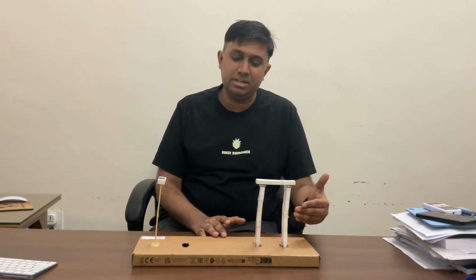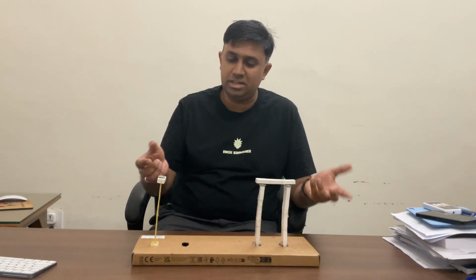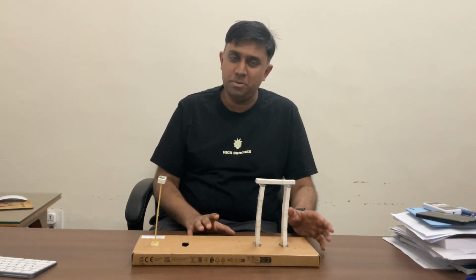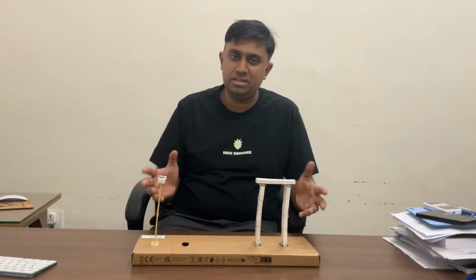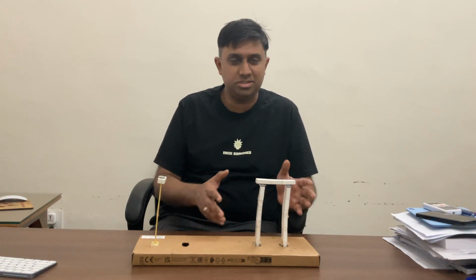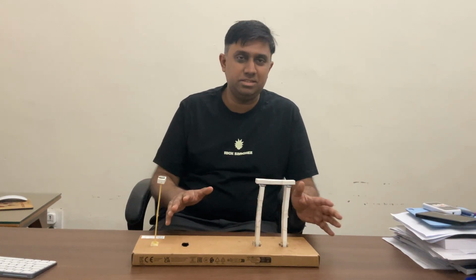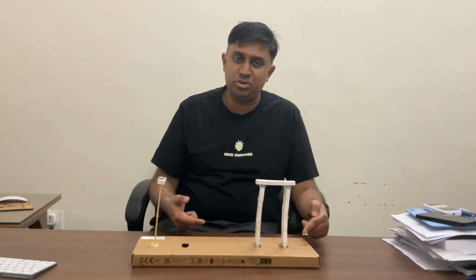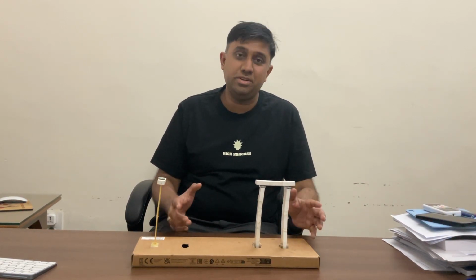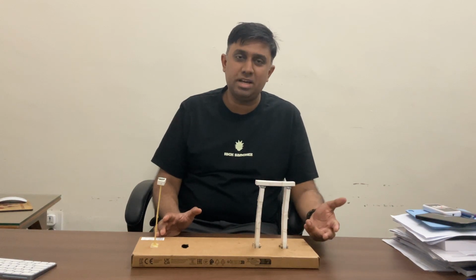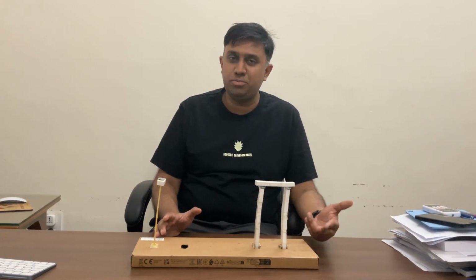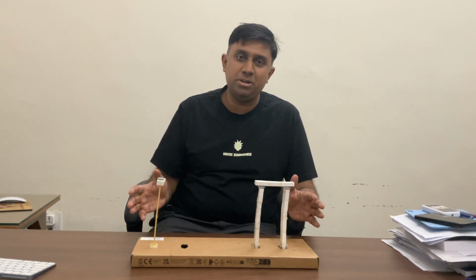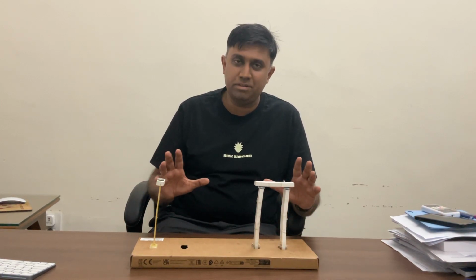This damping ratio is a dimensionless quantity which is reflective of after how many cycles the initial amplitude, let us say u naught, gets reduced to, let us say, 0.2 u naught, right? We are going to idealize the damping for this activity. There is a form of damping referred to as viscous damping, right? If we assume that, then it can be shown that the damping ratio is inversely proportional to the number of cycles taken for the structure for its amplitude to be reduced by a given factor, right?